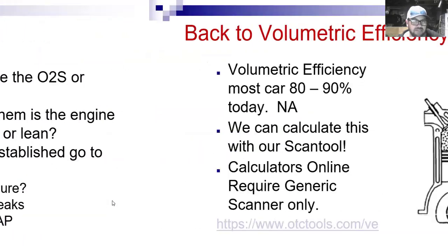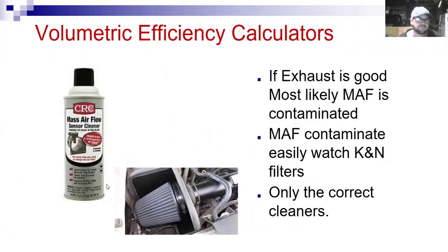So I'm trying to get back to my picture here of the cleaner. And they also don't like aftermarket air filters that are oiled because the oil can go back and coat that sensor element and throw them off. So yeah, you can clean them. Sometimes they get so contaminated that even cleaning them doesn't work, and you have to replace them. And if you're having to put a $300 or $400 sensor on a car, I don't know about you, but I want to be pretty sure that that's going to be the right diagnosis.